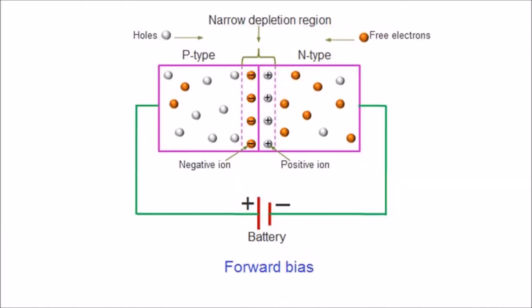The electrons which cross the PN junction into the P-type material will diffuse in the near neutral region. Therefore, the amount of minority carrier diffusion in the near neutral zone determines the amount of current that may flow through the diode.